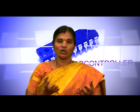Generally we calculate the baud rate as the system clock frequency divided by 12, because the clock frequency is generated for one machine cycle, then divided by the prescaler value 32. Finally this is divided by your required baud rate, and you get a decimal value. The decimal value should be loaded in hexadecimal into the timer, because the microcontroller executes only hexadecimal values. That is why we convert. So the baud rate calculation is also very important in serial communication.